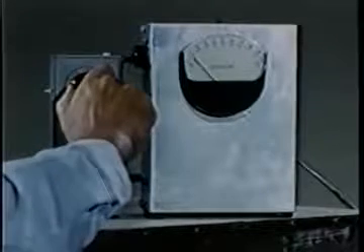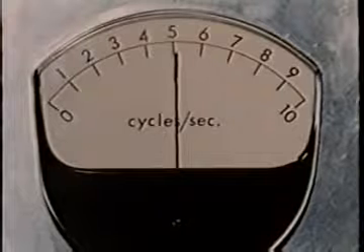In order to find the frequency response of amplification, we put in sinusoidal disturbances which we can control. We start the wave maker oscillating at 5 cycles per second. At zero airspeed, the waves are damped as they travel away from the wave maker. With the tunnel running, but below critical airspeed, we don't notice much change in wave damping. As we increase the airspeed and pass critical speed, we see the waves grow.